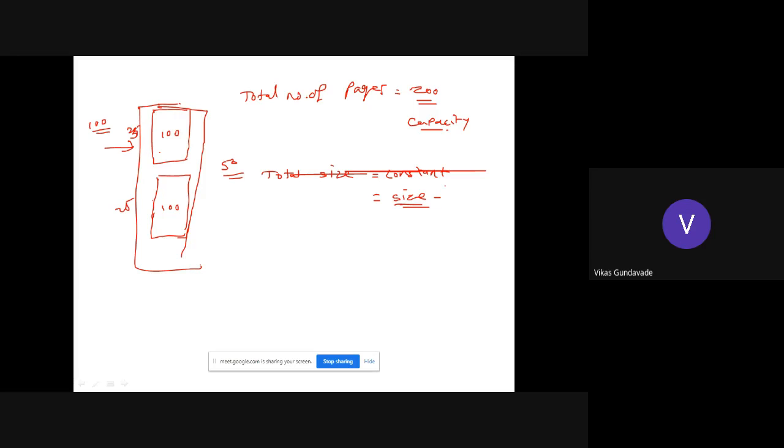Okay. So depending upon this capacity and memory, the equation can be represented as 2 raised to x by y. This is the capacity of memory. So x represents the address lines and y represents the word size. The number of lines available for x is nothing but the address lines. And the word size y depends upon the data lines, which are interfaced to the particular memory.